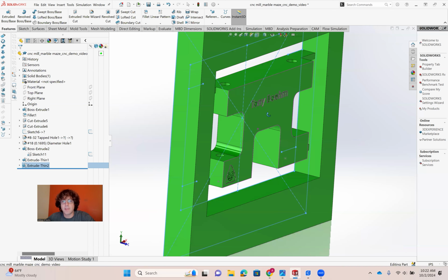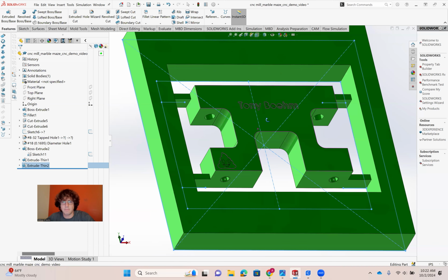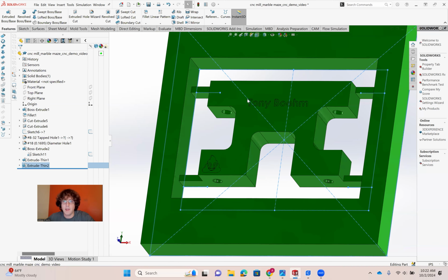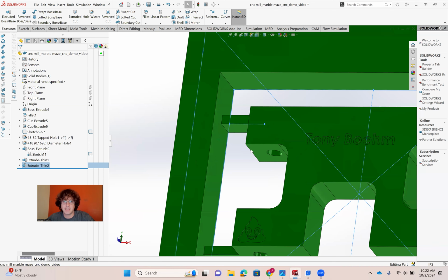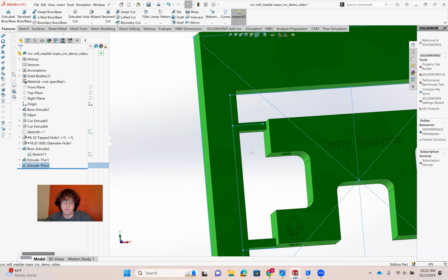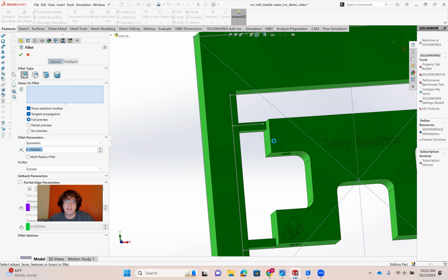Okay. And that would actually be enough for us to machine, but what I want you to realize is that when you machine anything with an end mill, I guess more specifically, wire EDM is sort of a different story, although you run into internal radiuses there too. But anytime you cut an internal corner, it will not be a 90-degree sharp corner like that. Okay, it'll always be rounded. So I like to accurately portray that if I can.